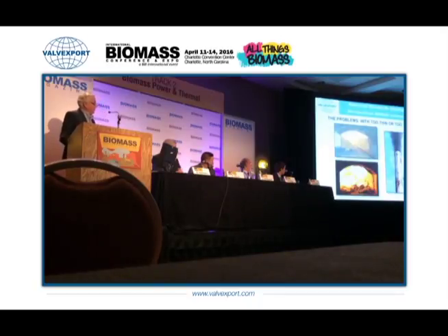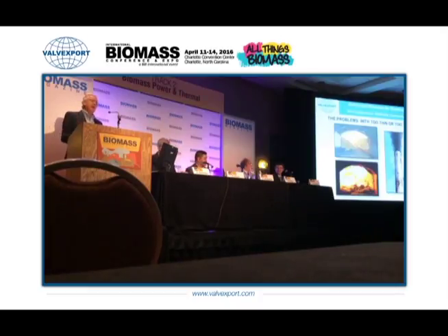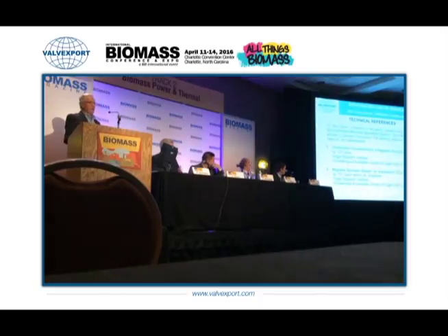Now, we were told that we should show this, but unless you clean the gases and you are not doing a good job at distributing the mass over the grate or having an efficient combustion, this is what we get, and we have worked a lot in hiding incomplete combustion. We have developed many things to hide what happens, and obviously there is a cost to that, both in maintenance as well as in power generation.